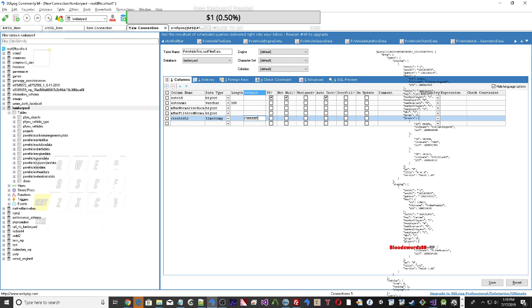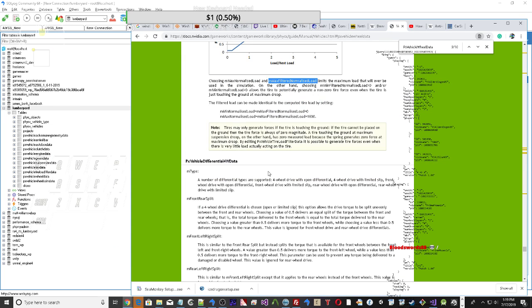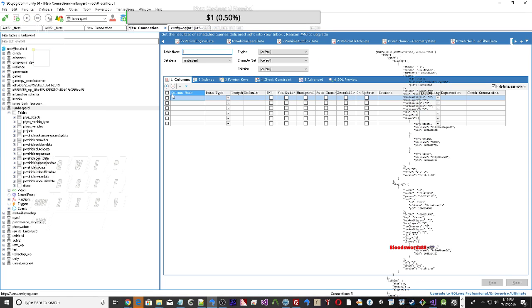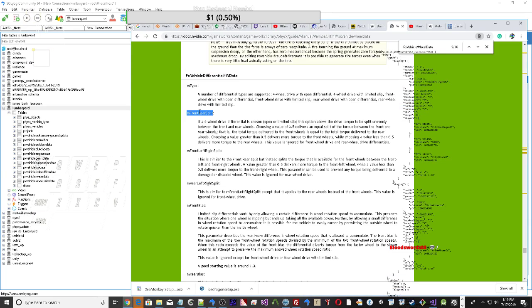As expected, the vehicle SDK also has a shutdown process which needs to be invoked. PX_C_EXPORT void PX_CALL_CONV PxCloseVehicleSDK(PxSerializationRegistry* serializationRegistry = NULL). This needs to be called before the PxPhysics instance and PxFoundation instance are released. That is, the order of shutdown is the reverse of the initialization order.